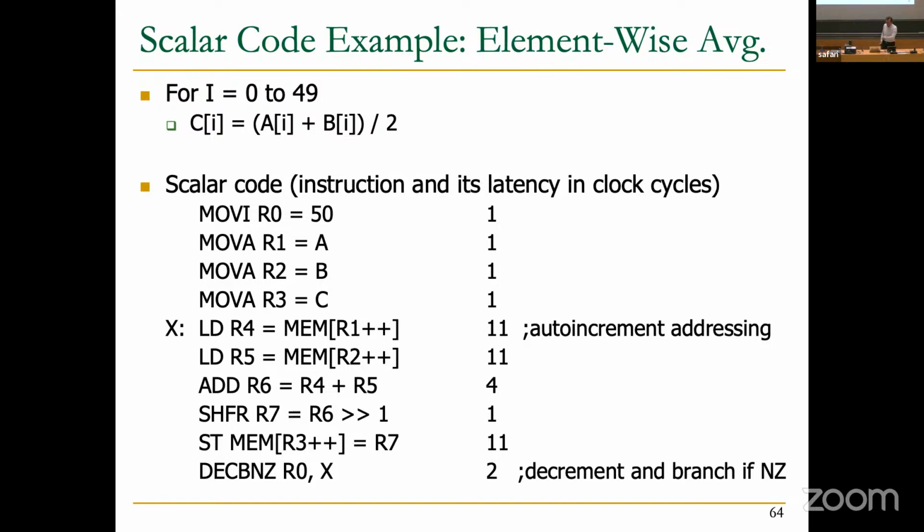Okay, let's get started. There were some good questions about programmability of systolic arrays and how much performance you would get. We did not cover a lot of programmability issues, but even for systolic arrays, if you really want to get high performance, you need to orchestrate your data, as we discussed, and make sure that you actually fit your matrix operations in a pipeline manner into this matrix unit, if you will, that we discussed with TPU, for example.